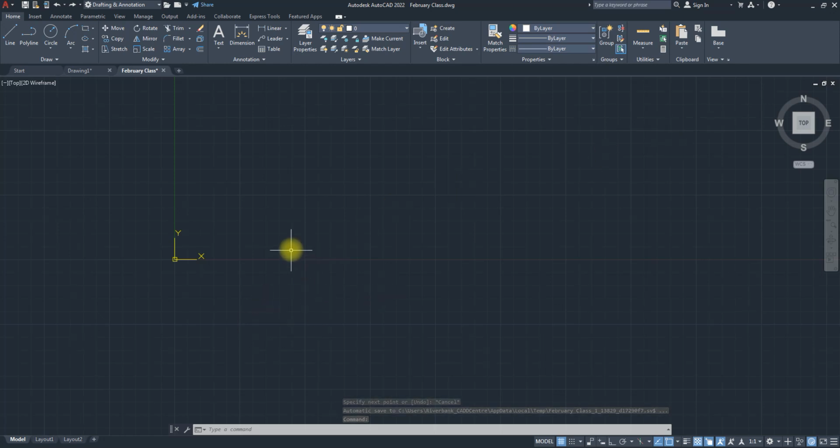So what we'll do is I'll close up all my commands by pressing Escape. Then I'll come to my grid. This is my grid and this is my snap. The shortcut for snap is F9. So if I want to bring up my snap, I'll just press F9. It comes up. Can you see it's on beside the grid? If I press F9 again, it goes away.